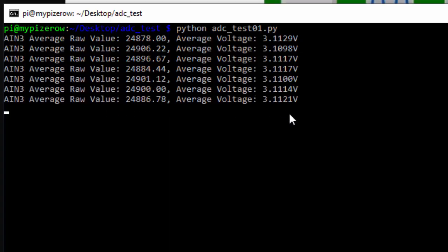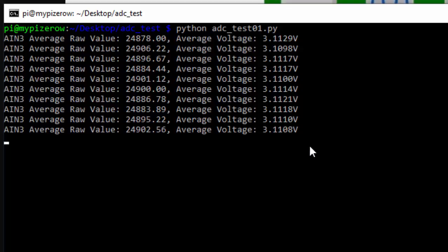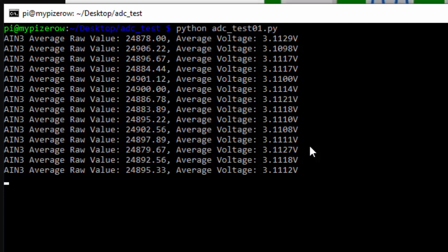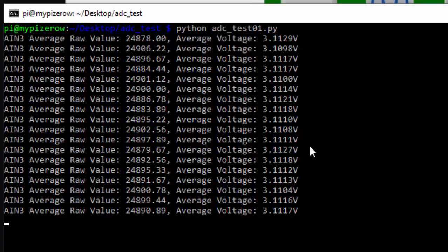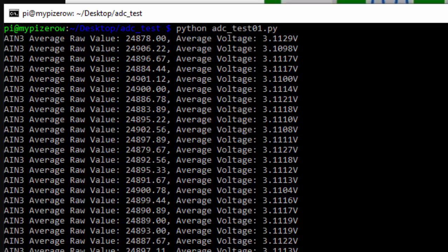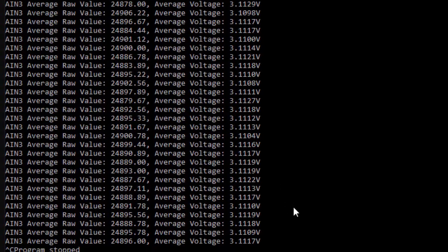and the voltages. I have added a 470K pull-up resistor on the ADC channel 3 pin. Then to measure the resistor which needs to be calculated, we will connect that resistor to the ADC channel 3 pin and a ground. So that is how it will become a voltage divider, and with the help of the simple voltage divider formula, we are able to read the actual resistor value.